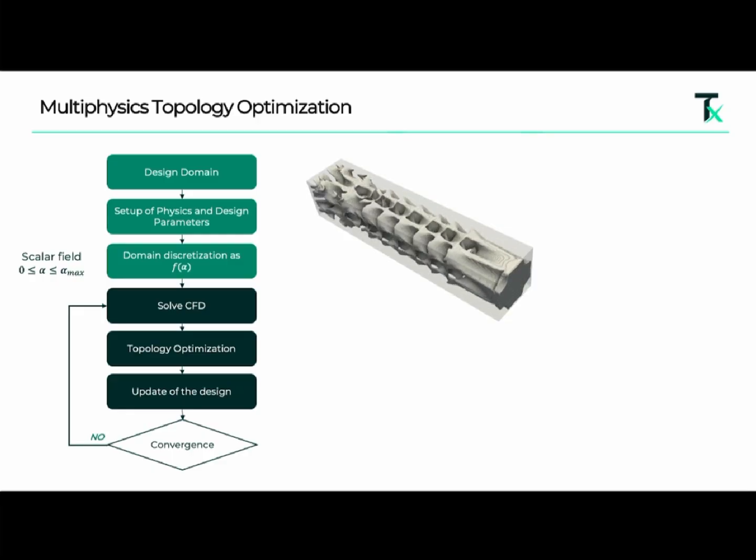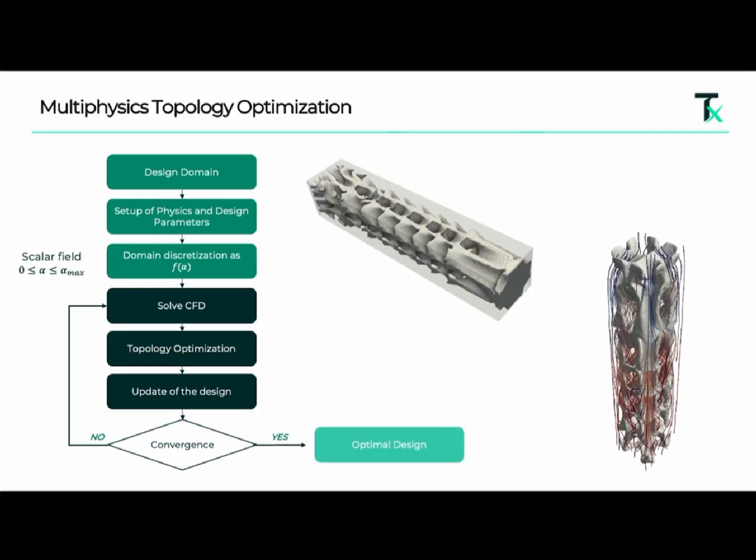So you see, eventually it converges to a design with loads and loads of little fins. In this case, we've got cold fluid coming in from the left, hot walls, and you're trying to cool the walls as much as possible. So it creates these fins, creates loads of recirculation regions. There's some streamlines. And so you get lots of convection, but the fins are designed to not cause any separation or turbulent losses, so you've got a very low pressure loss across the system. So that's the principles of what's going on.